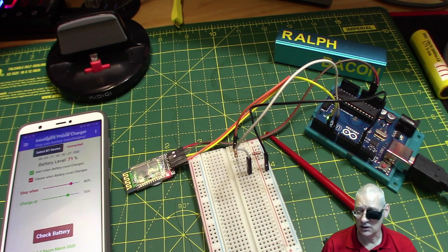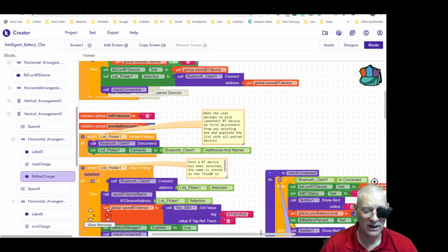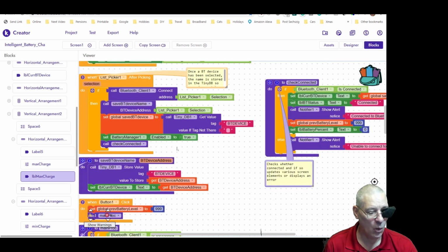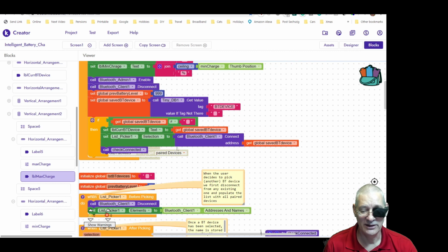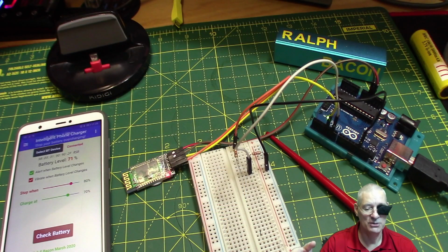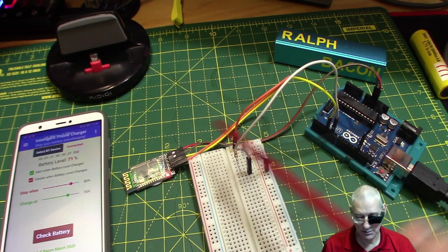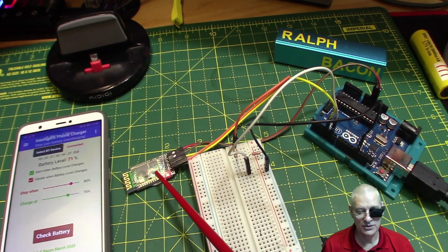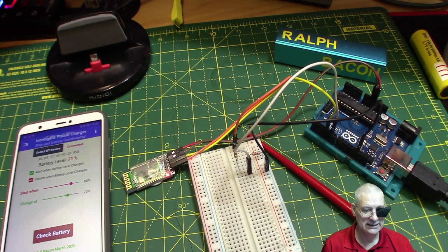And in fact, the code, going back to the code again quickly, most of this code, or a huge amount of it, is what to do when things go wrong. So, what happens when you can't connect? What happens if you can't transmit? Or what happens if this module here is no longer receiving commands and things like that? Now, the only time it knows there's a problem is when this tries to transmit a value.